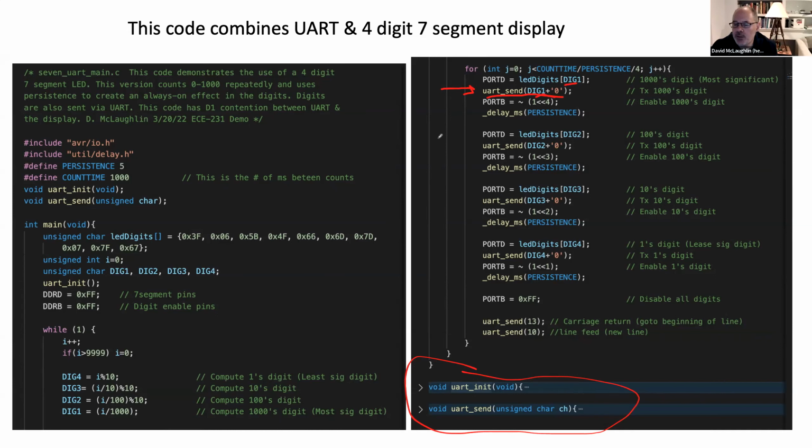How do we solve that? Well, we have to avoid using those pins. Certainly the transmit pin if we're just transmitting via UART, or if we wanted to actually take in input from the keyboard, we haven't done that yet, but if we were using our serial monitor both two-way, someone working on the keyboard and we wanted to receive information from the keyboard, that would be using another of these pins. Okay, so the solution is to avoid PD0. If you're going to be using the UART, don't use PD0 for GPIO. So there are many ways that you can do that.